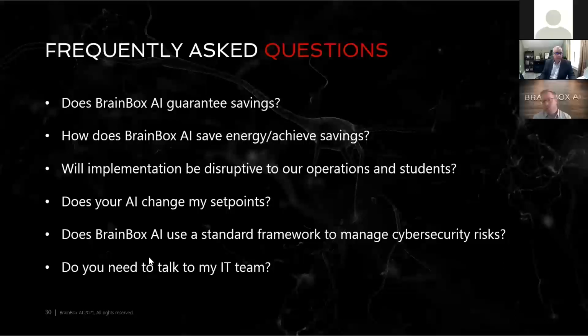So we will change set points on the air handler or set points on the chilled water system, stuff like that. But it's all inherently to keep that temperature at the zone more often. In fact, we're seeing in most of our data, we see 50 to 60% increase in temperature staying in the dead band because we can anticipate those weather related forecast events.